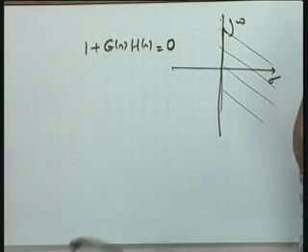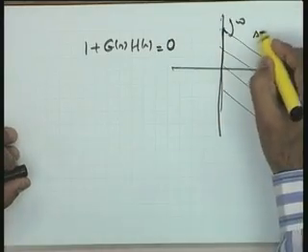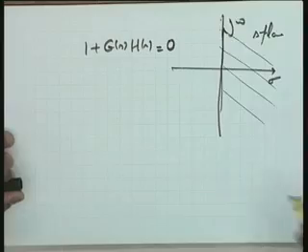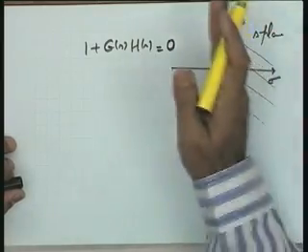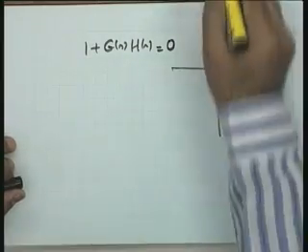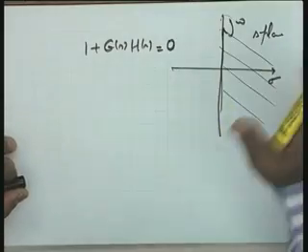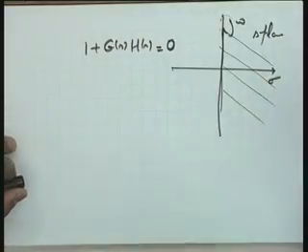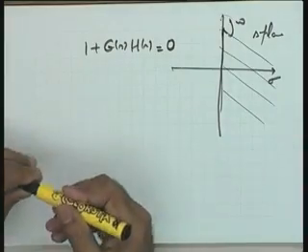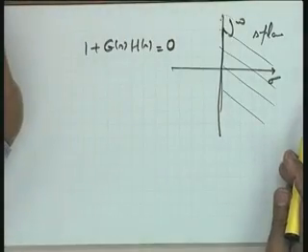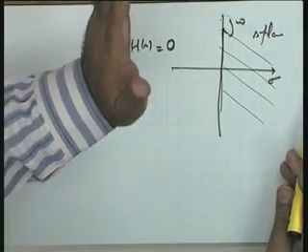I repeat this point that this is the S plane I have considered. In this S plane all the S points are there. You consider the region in the right half of the S plane including the imaginary axis. The marginal stability case, initially let me talk of instability, let me take this as the unstable case. So stability will mean that all the closed loop poles lie in this particular region, the left half of the S plane. This is my stability definition.